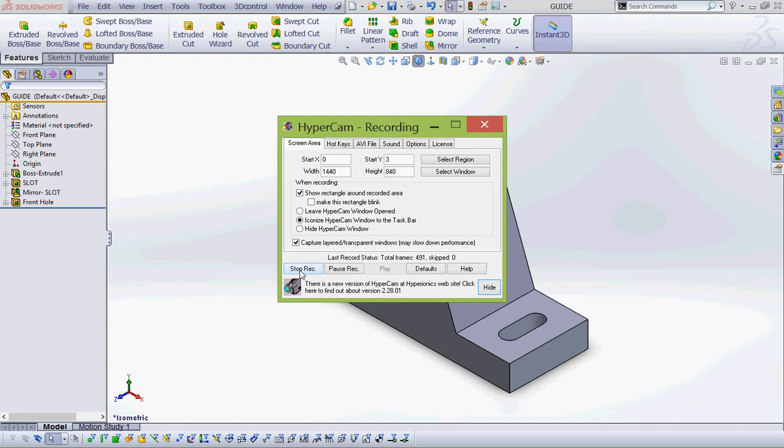I want my circle to be vertically over that origin. Okay, and it's going to be diameter 10, and it's going to be 29 from the bottom. Okay, now mine still says underdefined, so what I'm going to do is add a vertical constraint between the origin and the center point.